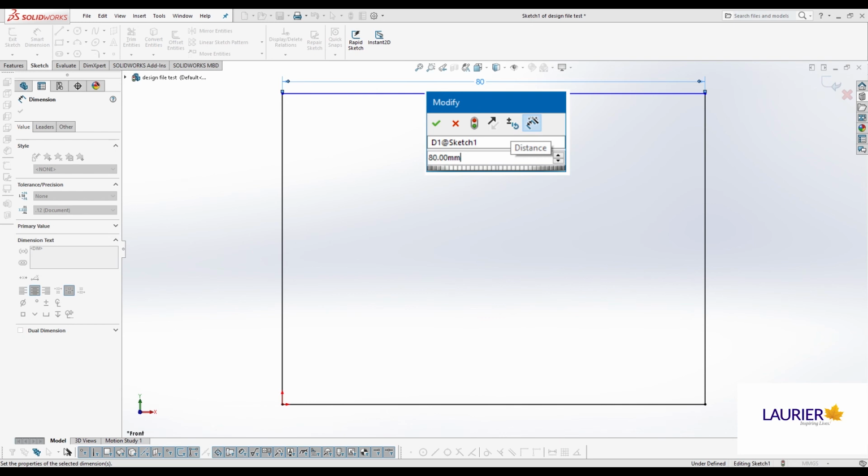So what does that mean the default unit of measure that we're working in is? Yes, it's in millimeters. That's something we can set. We're free to change that for every drawing. We can set a different default for every drawing as we need it, but because both our laser cutter and our 3D printers work in millimeters, we tend to just leave it in millimeters unless there's some special need, such as working with stock materials from a machine shop or something like that. If we buy steel, we're going to be buying 1/2 inch plate, not 10 millimeter plate, not here in North America at least. So we now know that we don't have to put in units if we just wanted to go to the default unit.